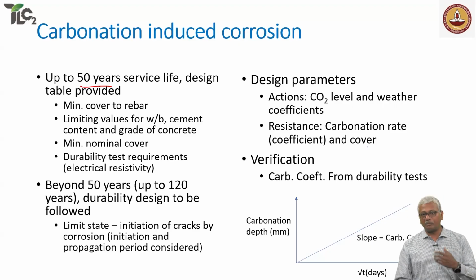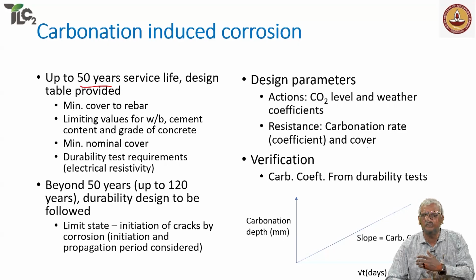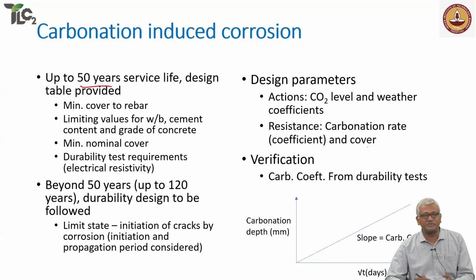A limit state probabilistic durability design method will be done, which will involve design parameters like the carbon dioxide level and weather coefficients. For instance, even if we have high carbon dioxide levels, our humidity, carbonation does not become a dominant mechanism. Whereas if you go to Bangalore or Hyderabad, those are ideal conditions for carbonation related.